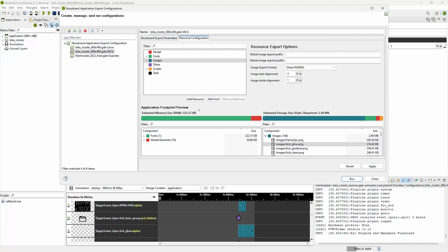It's a very good way of leveraging the DMA engines and other hardware on the target board to offload the graphics processing. Most of the rendering operations are read, modify, write of pixels. So we're looking at regions and blitting and alpha blending. This is a really good technique, and it's a really important way of getting more performance out of your target. Okay, so those choices are made. I'm going to switch that back. You can do that on an individual image basis or at the top level.